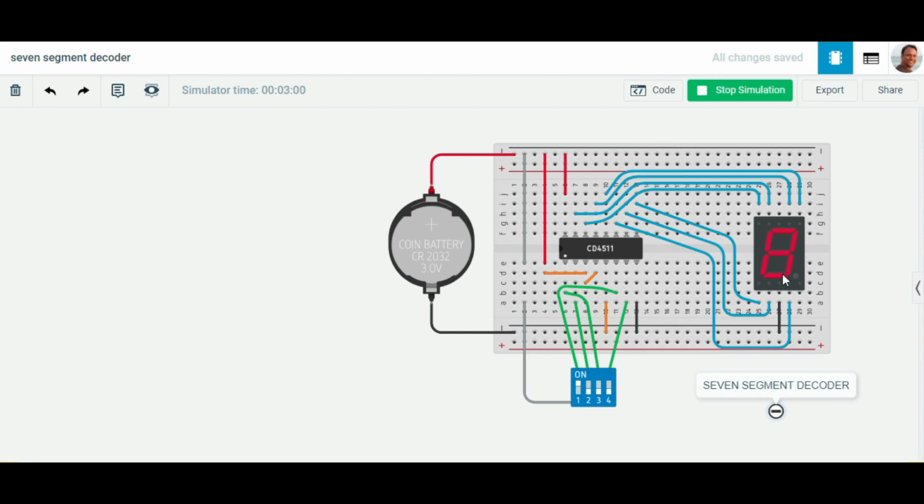So this is a real life scenario where we can check our 7 segment decoder. In the case where a particular segment is not glowing for any of the inputs, that means that segment of the 7 segment display is not working properly, or it may be damaged. So remember this, and we can see that our circuit is working properly.